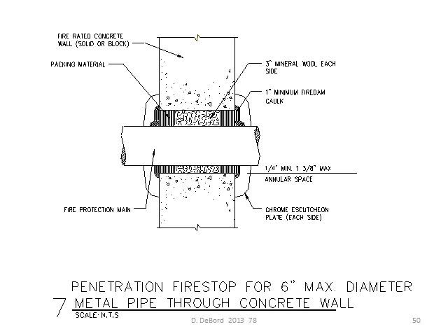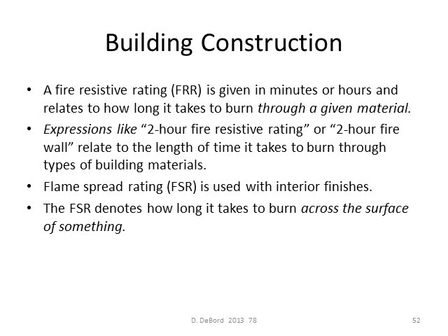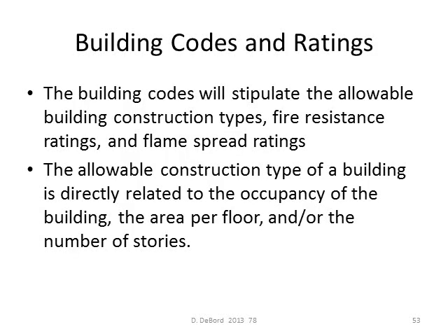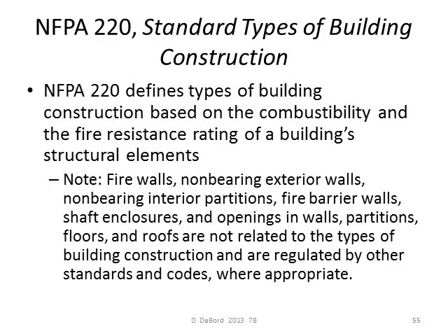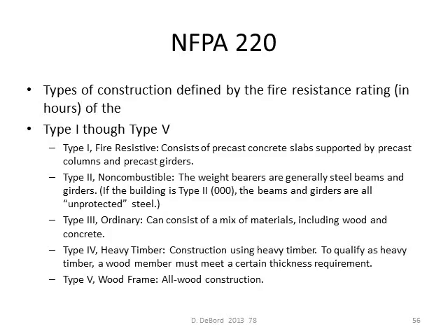This is important too. It's a fire stop penetration for a pipe going through a concrete wall. We don't want the fire to be able to get through around the pipe. We've included a lot of things here about building construction. Some notes that I think you should take a look at, or some additional information, testing, standards, etc.